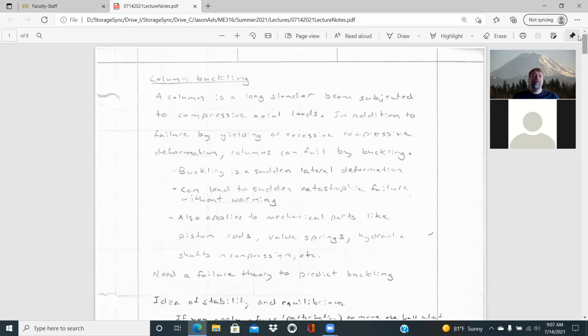A cable or rope is not able to withstand any type of compressive loading at all. It'll simply bend and deflect. So they can only use cables for tensile loading applications, and compressive struts for locations where there'll be compression in those members.